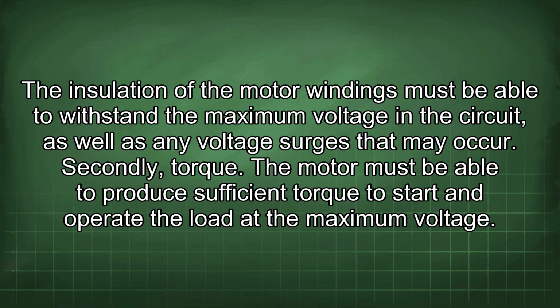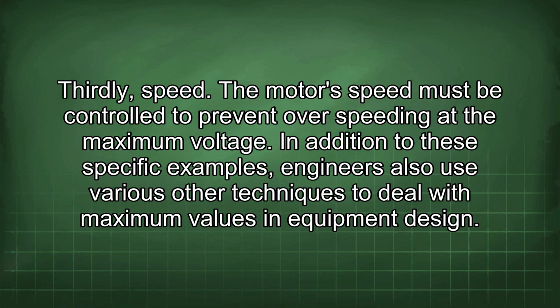Secondly, torque. The motor must be able to produce sufficient torque to start and operate the load at the maximum voltage. Thirdly, speed. The motor's speed must be controlled to prevent overspeeding at the maximum voltage.